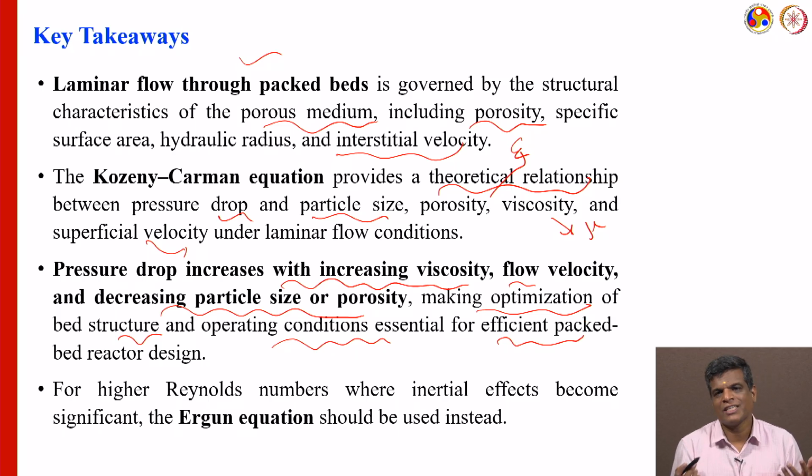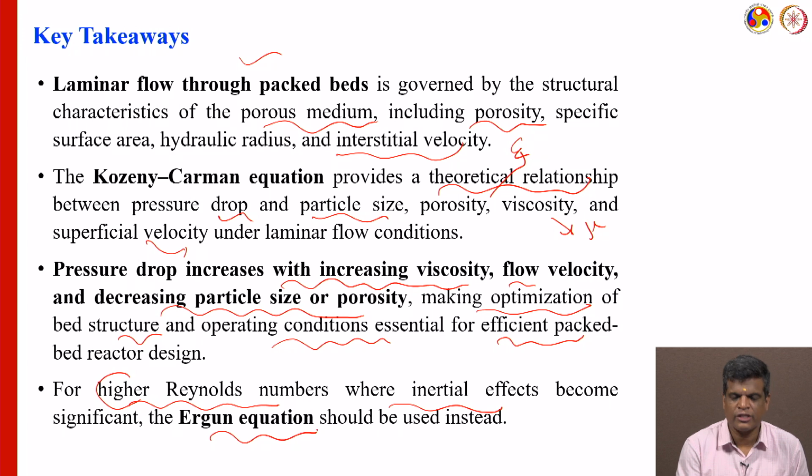So far we discussed laminar flow. When you use a higher Reynolds number, the inertial forces become dominant and the viscous forces are no longer dominant. Whenever we go to a higher Reynolds number, we have to use the Ergun equation. Thank you.